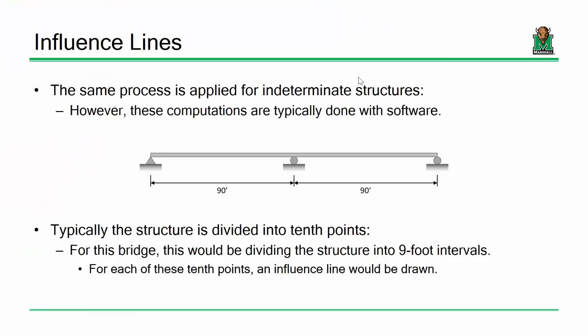All right. Okay, so what I mean by that, where'd my pen go? There we go. So keep in mind that throughout everything I'm about to draw, my point of interest is right here. Now what that influence line was telling me is that if I place that truck, I don't know, somewhere right here, that I'm going to get positive bending. Now why am I going to get positive bending?